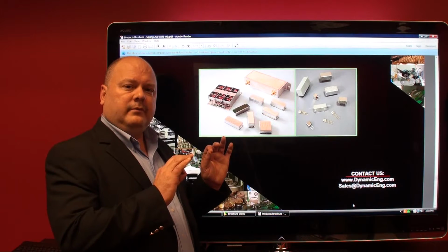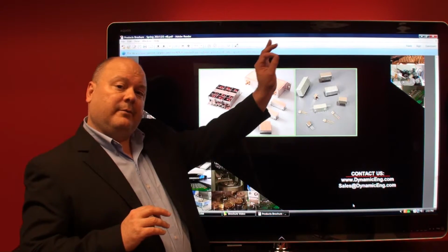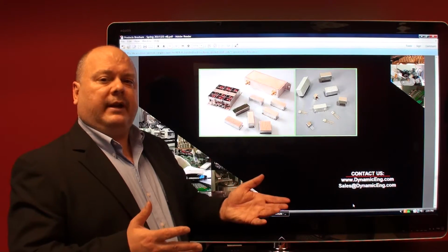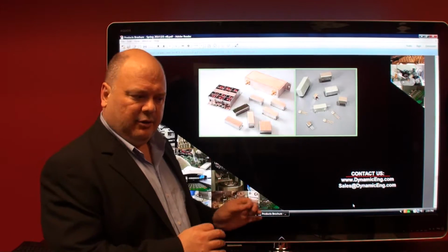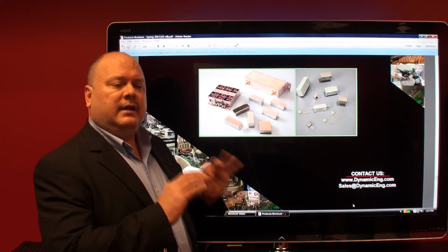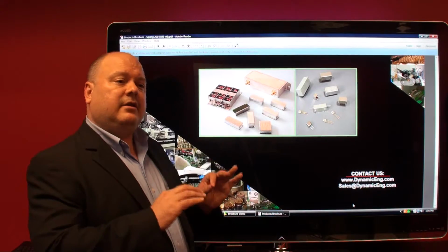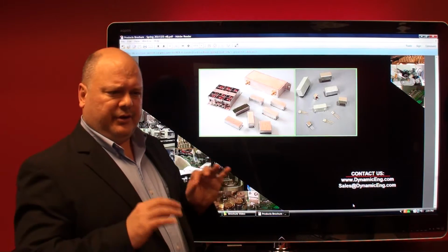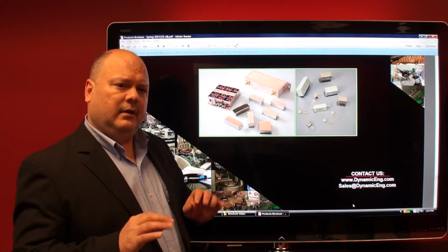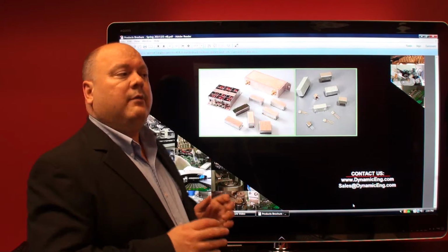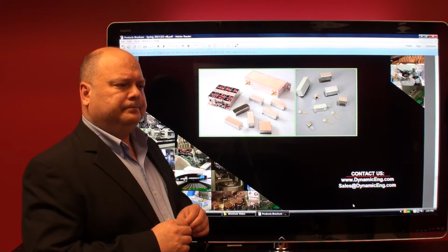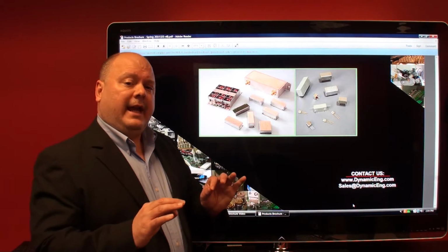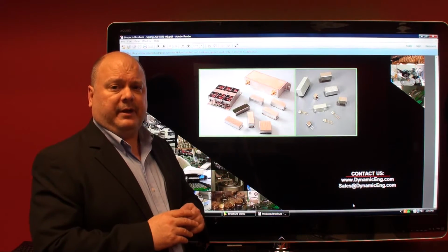So the audio or the data or the voice that's coming in from the carrier on a VHF radio will first be upgraded, uploaded, uplinked to an IF frequency. So that information will be modulated onto an IF frequency of, say, 70 megahertz or 140 megahertz. There's a few very common frequencies for IF, 10.7 megahertz, 21.4 megahertz. That information will be modulated onto an IF carrier, and again, that dictates your channel spacing.